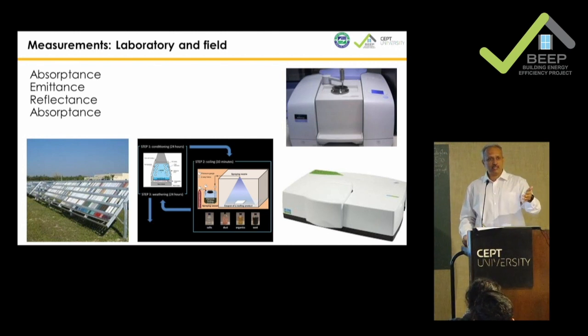So what we do is we measure the fresh SRI of the paint, and most of the codes, ECBC, GRIHA and IGBC, talk about SRI values. We call it the virgin or first-time measured SRI value. But as you know, the roof will get impacted by dust, salt, and pollution, and it will degrade.